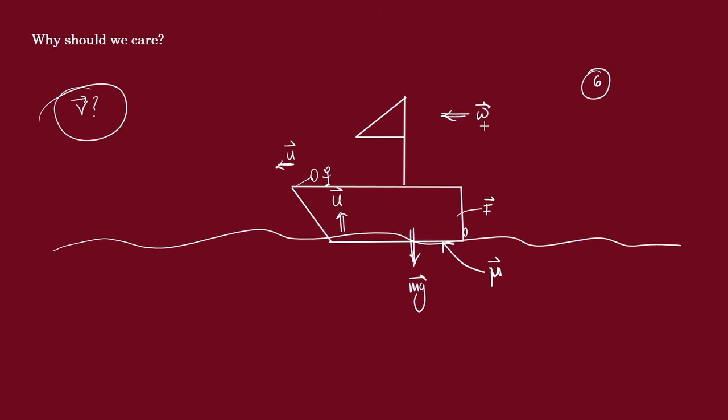And the way this is done is that we'll keep everything constant and vary one. So let's say we keep everything constant and vary the wind, get our values for those, keep everything constant and vary the weight of the boat, get our value for those, and be able to see if we can magically come up with a relationship with 6 different unique table of values. But the advantage we now have with dealing with dimensional analysis is that we reduce the number of independent variables, usually from 6 to something like 3 or 4, or sometimes even 2, okay, depending on the parameters of the situation. So once you now have less variables, you're able to come up with a simpler way to experimentally determine whatever it is you're trying to generate an equation for.